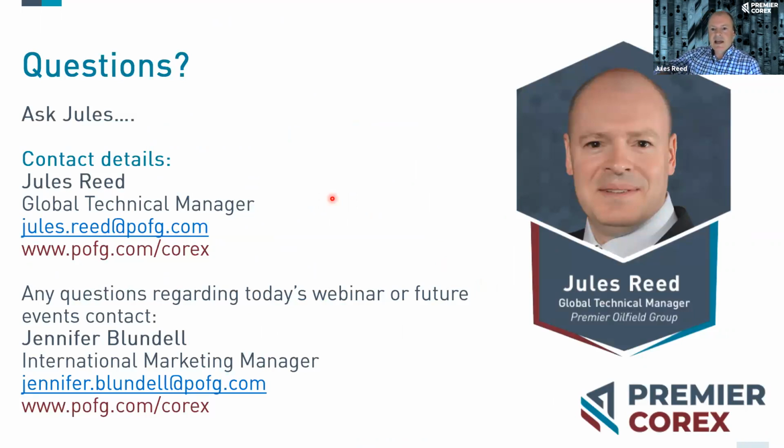Residual oil saturation is only one of the targets of EOR. So EOR could reduce residual oil saturation even further than it would be normally, but you're also trying to improve sweep efficiency. And in the laboratory, we can't determine sweep efficiency from a plug. That's done by characterizing the reservoir and understanding the different layers and the different properties of those different layers of your reservoir. So it usually comes from the geology and the routine core analysis and the petrophysics, determining the different layers and structure.